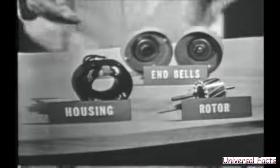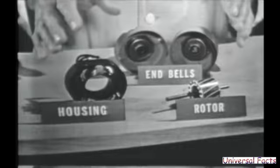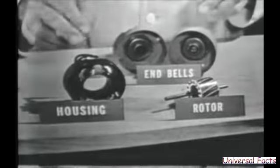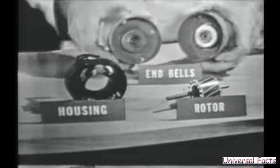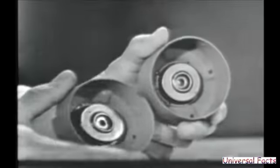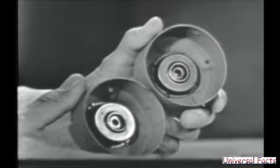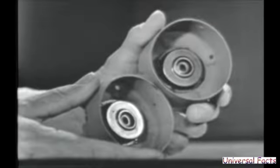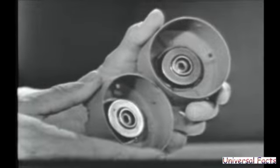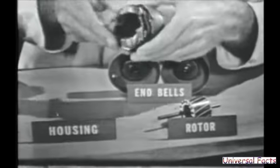Bob? Okay. This is a typical induction motor disassembled. Now, as we've said, it's very, very simple. We have the 2 end bells, the stator field windings, and the rotor. Now, let's take a look at these end bells. The end bells are used to house the bearings or the mounting devices that hold the rotor shaft in place. Now, notice there are no brushes or complicated brush holding devices at all. Just simply hold the bearings. And also inside the housing, or inside the end bells, we would find the housing that contains the stator field windings.